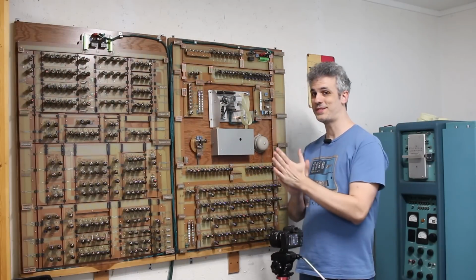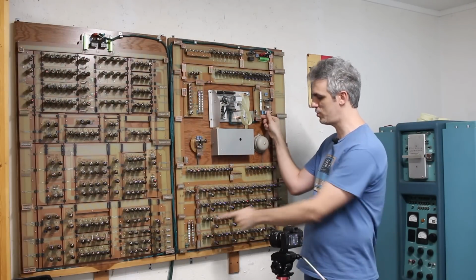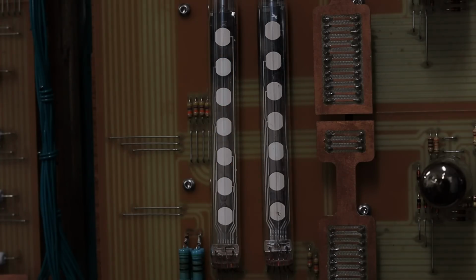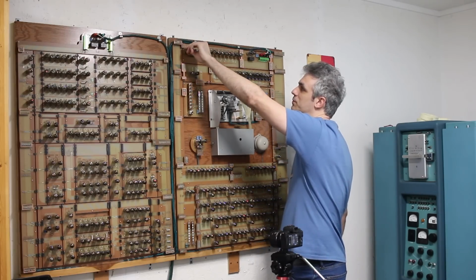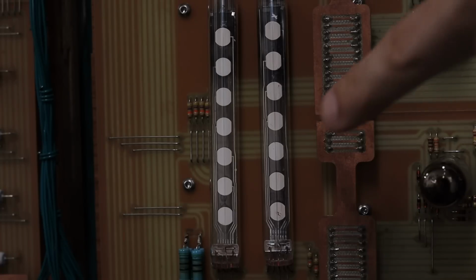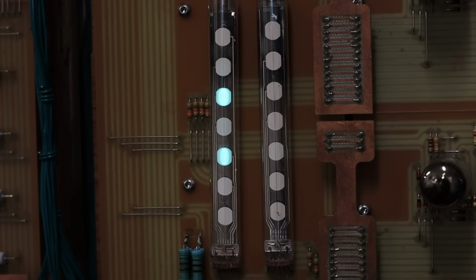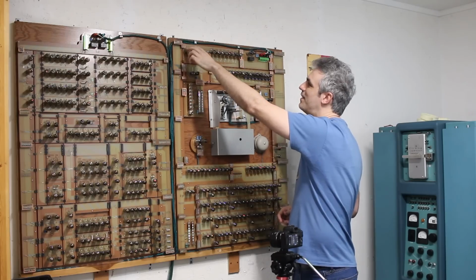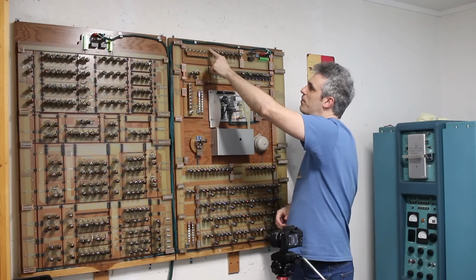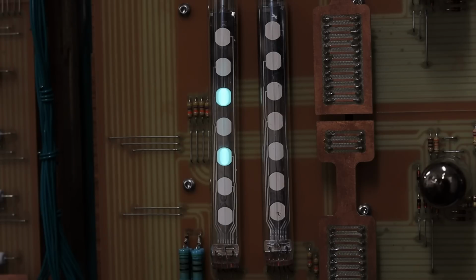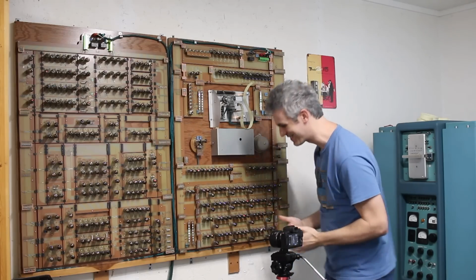All right, here we go. Let's give it a test. We'll run it. It should clear out anything that's down here. Yep. Let's go ahead and put in our first value. We'll just do 5, I guess. We should see 101 show up on the output register. That's definitely an improvement. And let's add 1 to it. So I'll flip the far bit and just the first bit. We should see that become 6. Yes, all right. We just did 5 plus 1 equals 6.